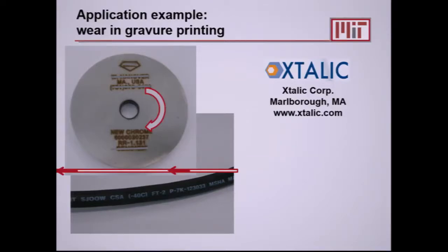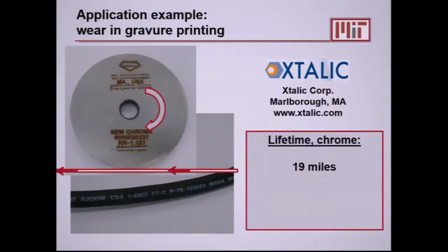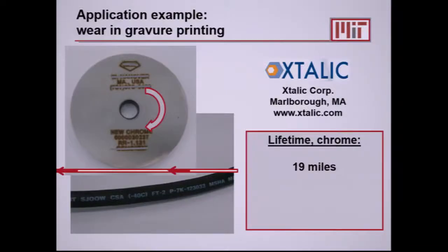So this product is a classic example of what we use hard chromium for, right? So you never see this, but it touches your life in a million ways. And the way they use chrome here is that they make this wheel, they emboss the letters, and then they chrome it to make them hard, because they're going to spin very, very fast, and they're going to print 20 miles of this wire. And it's going to be smacking and wearing, and gradually you beat those letters down until this is insufficiently legible. And that's the failure mechanism of this guy.